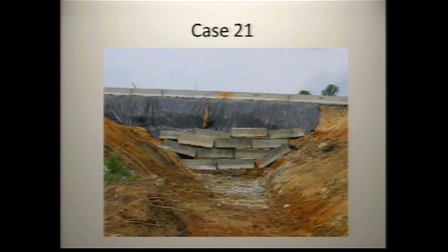Let's start with the slopes. Unprotected, right? I mean, there's a risk level 2 site. You've got to have straw wattles at certain intervals. So the slopes, I can tell from looking, there's no erosion control, but there's no sediment controls on the slopes. If you want to buy into the visqueen, I guess that's your business, but at least fix the hole in the middle of it and continue it all the way over, correct? I mean, they just lost interest there at some point.